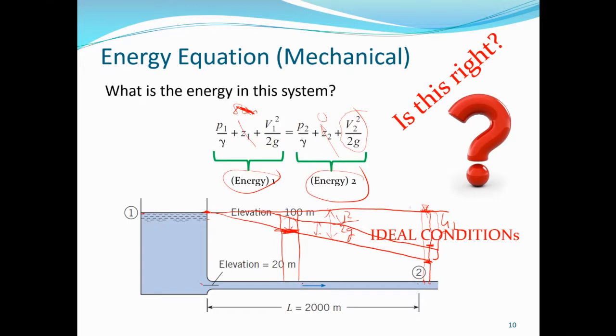But when you put a pitot tube, you remember we did the pitot tube, which measures both the static pressure, that's the piezometric pressure head, and the dynamic head, water will rise up to this level because the pitot tube measures the velocity head. But water will never rise to the initial level, which is this, because of the head loss. And head loss is simply the conversion of the useful mechanical energy to waste thermal energy because of frictional heating. As it is flowing, you realize the temperature is slightly raised because of the head loss.